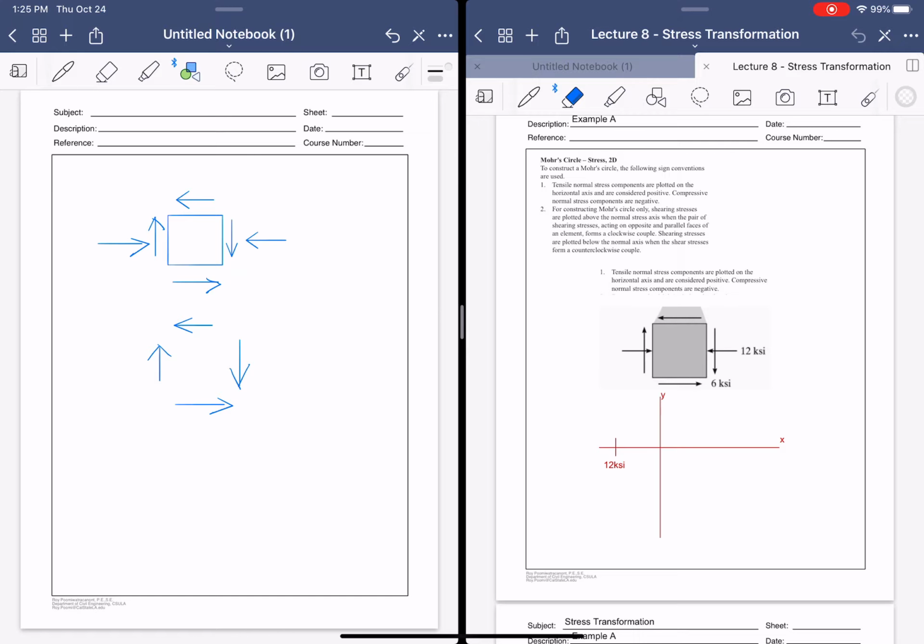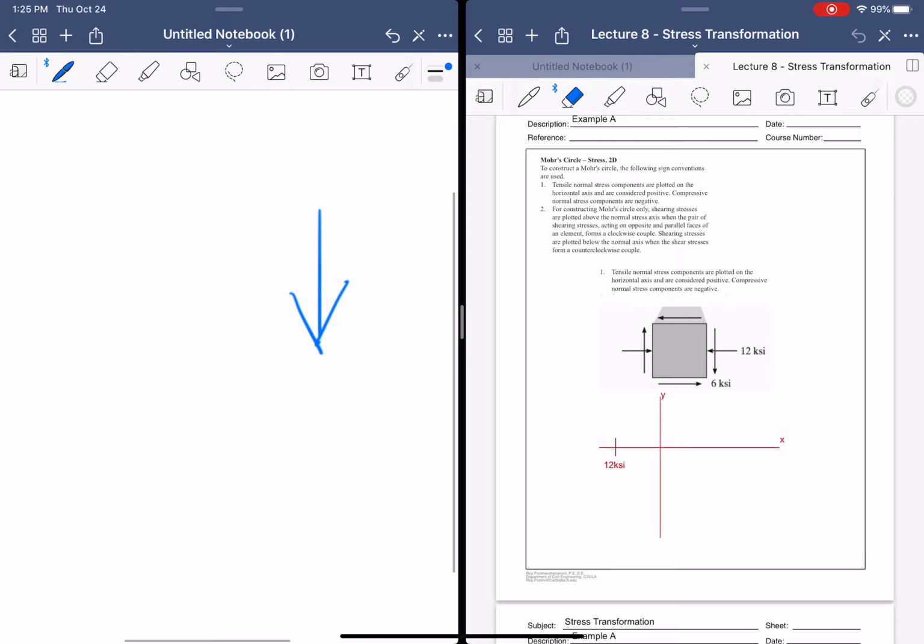Now, if we were to erase it so that we're focused on just 3, okay? If we talk from an equilibrium standpoint, if we have a shear here, we know that we have to meet equilibrium, therefore, by doing an equal and opposite. That's one. Once we do this, we'll do the check. Sum of the forces in the y. Does that equal 0?